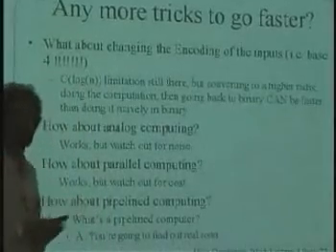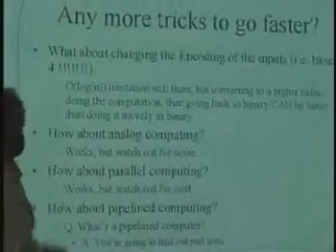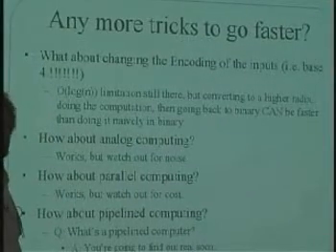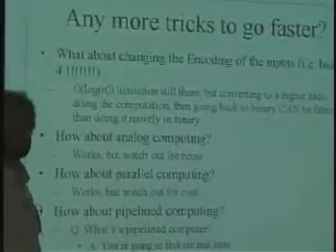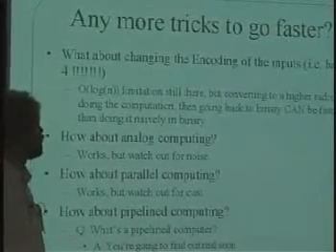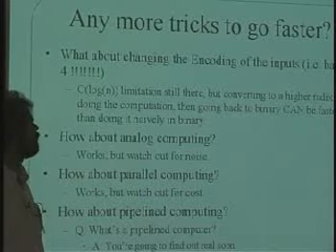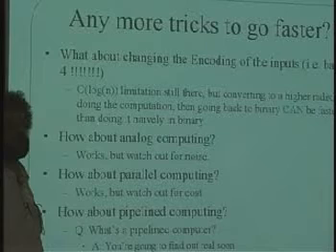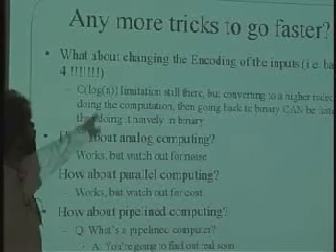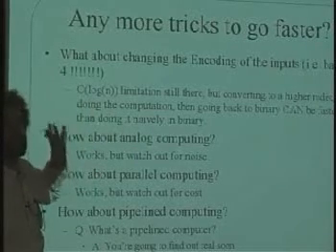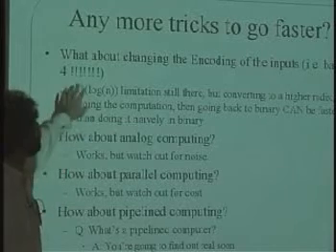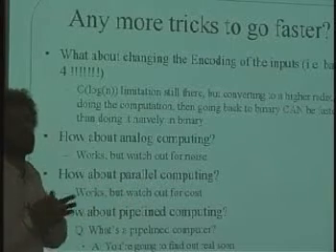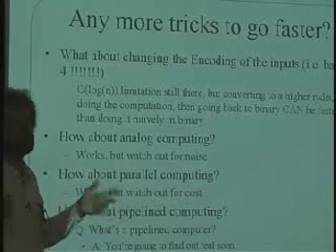We've been only doing things in base 2. Well, what if we changed it to base 4 and operated in base 4? It turns out that you can actually build a faster adder if you do things in base 4 or even base 10. Usually they don't go higher than 10, but this recoding to a different base is something that is commonly done in the high-performance adders that you see in real high-end chips. And you're still up against order log n if n is big, but the constant factor can go down. Recoding to more bits always means that the amount of hardware you dedicate to doing the add grows very, very big, but the speed can go up.